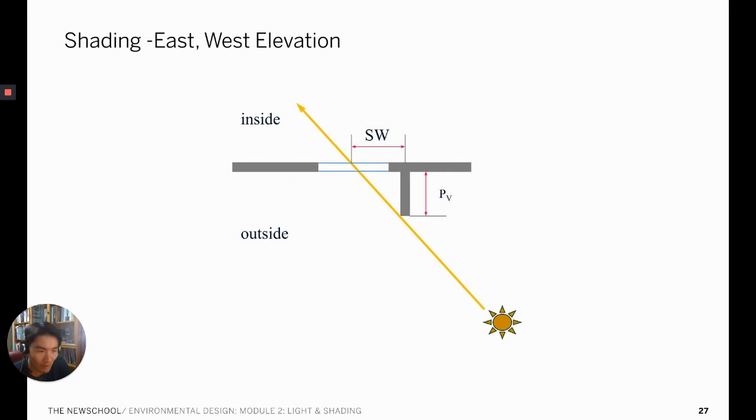East and west facades are more related to the solar rays reaching during the morning and afternoon. During this time, the sun's motion is more horizontal compared to midday. Switching to vertical fins performs better if the geometry is properly designed based on the dominant solar angles. However, east and west facades should also address the altitude angle of the sun at the same time by adding horizontal shading or morphing the vertical shadings.